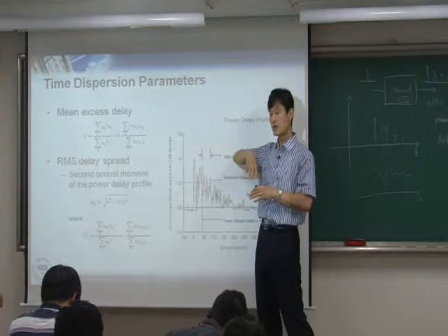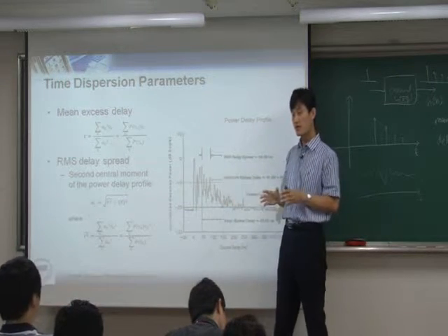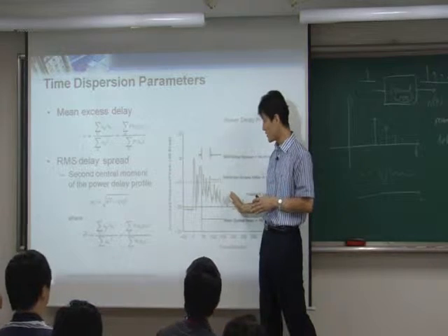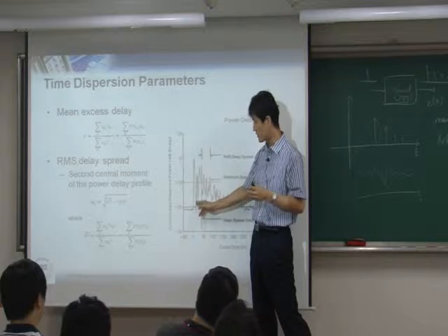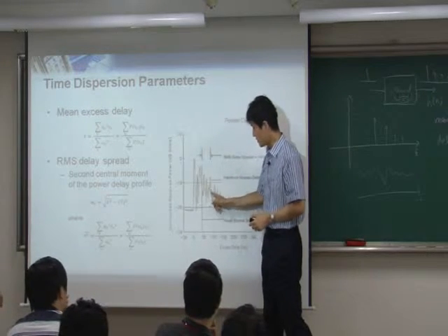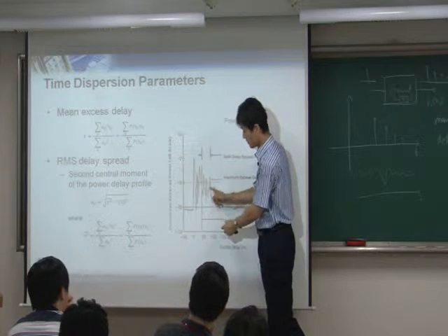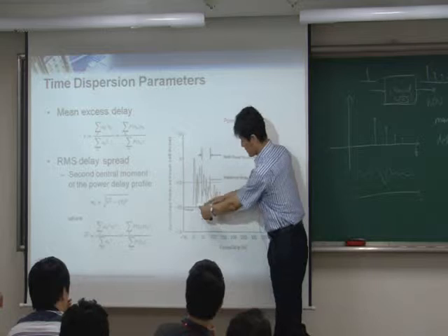Propagation is related to the path loss and some other things. In this case, we are talking about small scale fading. So all the delay we are talking about is compared to the first one, the line of sight, right? And so this much is delay. For this component, delay component or multipath, we have this much delay. So each component will have a different delay.